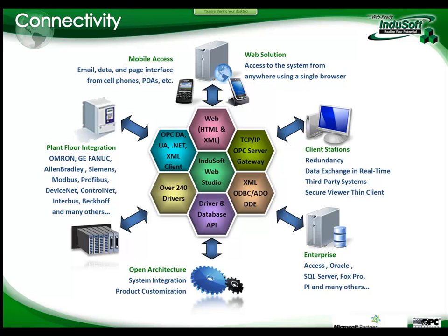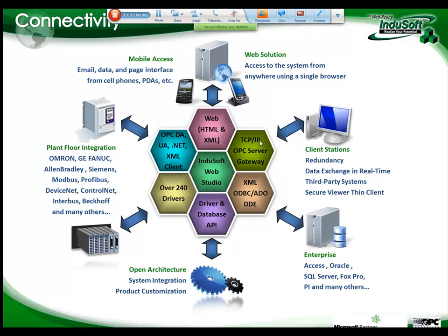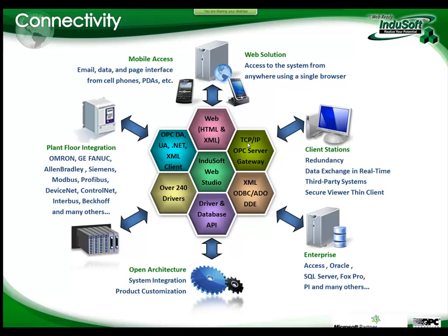And we also offer gateways for connecting natively to other SCADA systems. That means you don't need to change anything on that other SCADA to communicate with InduSoft. We provide a way to communicate between different InduSoft applications through Ethernet, through TCP/IP. That's our TCP/IP task. And we even offer an OPC server as part of the package, a DA server.